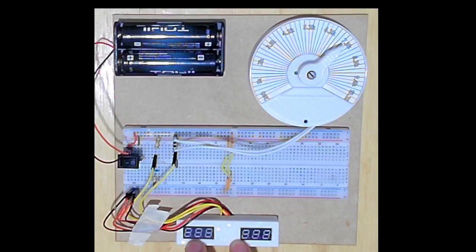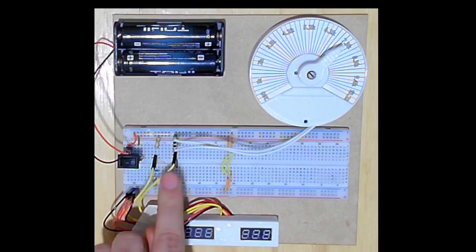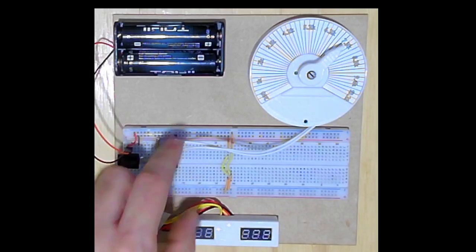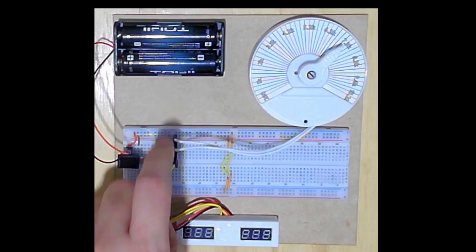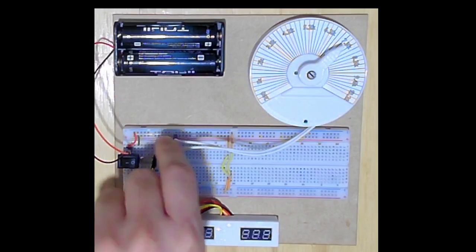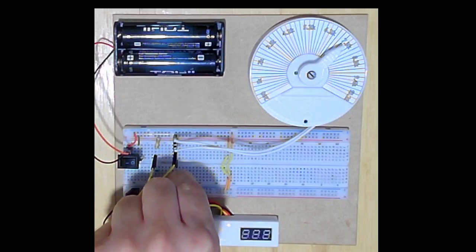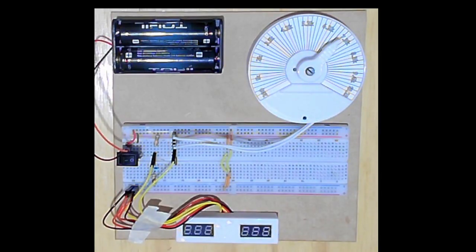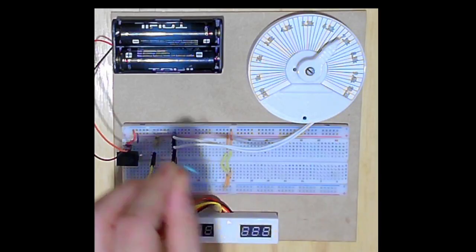Here I have two voltmeters, right? The idea in the lab, you will have a multimeter and you can read the voltage between these two nodes, the yellow cables. Right now, I am reading the voltage between the first two resistors and the voltage between the second two resistors, R3 and R4. If these are the same, I suppose that I have the same relationship in resistors, right? So here I have the same resistors. Then I am expecting that whatever value I got here will be the same as here when these two voltages are the same, right?